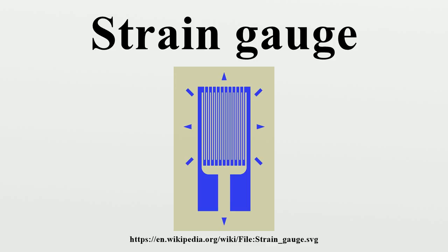If a strain gauge is loaded beyond its design limit, its performance degrades and cannot be recovered. Normally, good engineering practice suggests not to stress strain gauges beyond plus or minus 3000 microstrain.